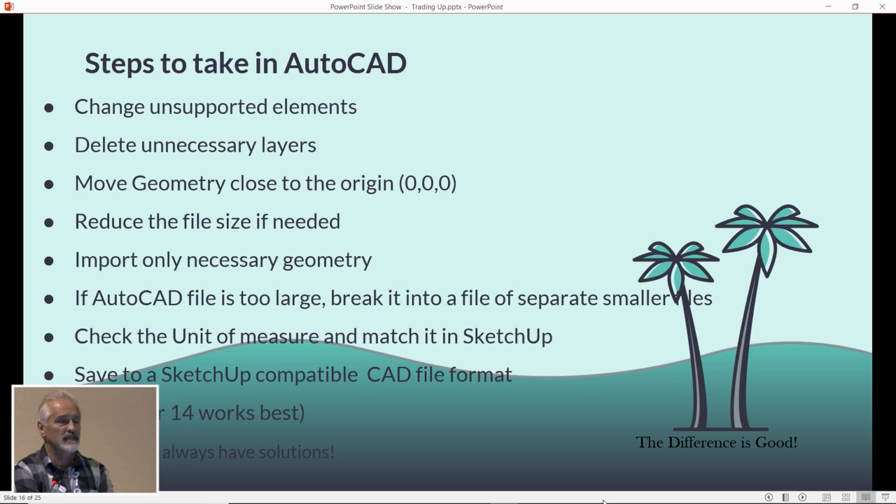How do you reduce a file size in AutoCAD? If you take an AutoCAD file, you can purge a drawing. You can take an XREFs file that is a reference, and you can put it live in the drawing and clean up the drawing. You can audit the file. AUDIT, if you're familiar with that in AutoCAD, it is a fix repair command. AUDIT, enter, yes, enter, fixes problems. Purging is a good one. Reducing the size is very good.